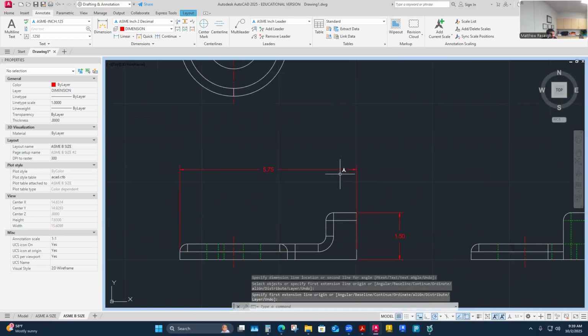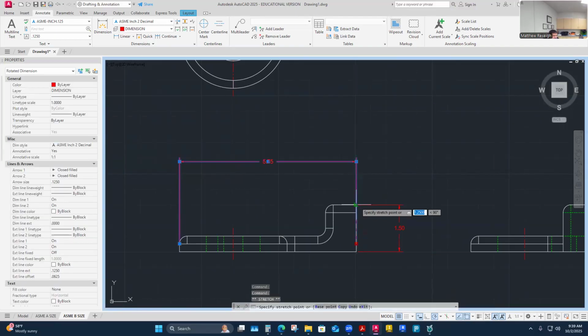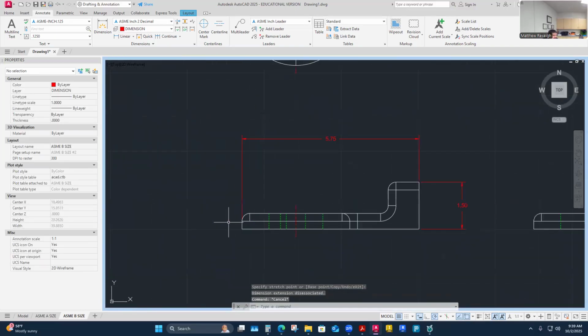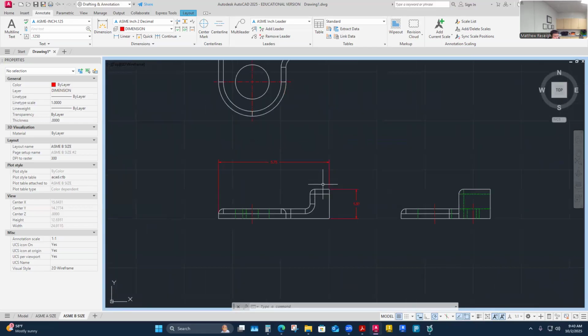That's another overall. If I leave it there, then I might want to say, well, which one is the datum and which one is where I'm measuring to, like which is from and to, like a gift package, to and from, return to sender. In this case, I would probably pick this right side surface as the datum, and this might be pulling from there to there, because it is a pretty good, controlled surface I could pull from. Essentially, my datums here are surfaces. They're not center lines or whatever.